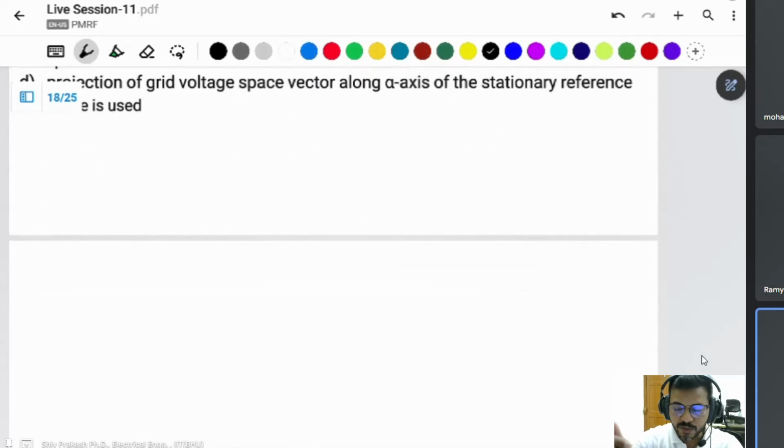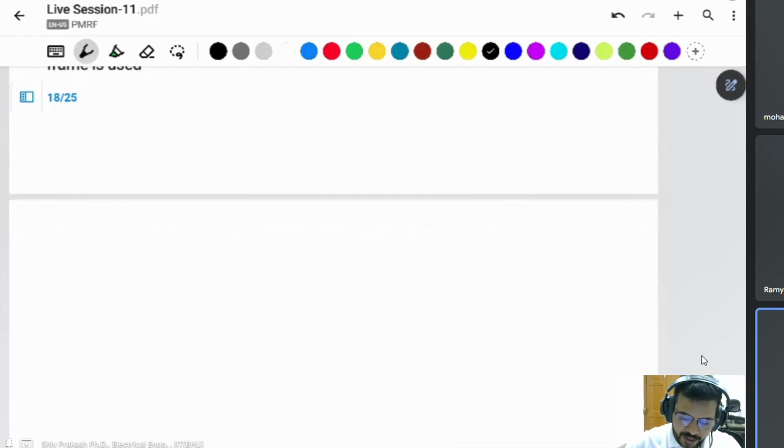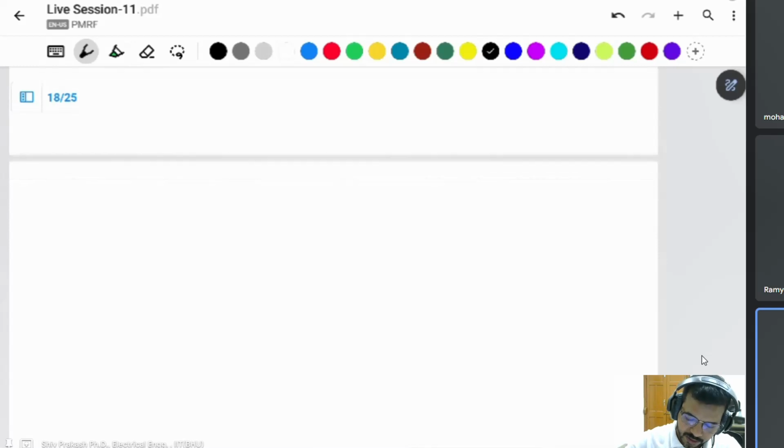Then this is eventually used for voltage, not current, because the current may have some harmonic contents. There are also some differences in angle, and the frequency may be the same, but there are some distortions there. That's why you use a voltage reference only. Take a voltage reference and find its angle. Then how can you find the angle of the voltage only?